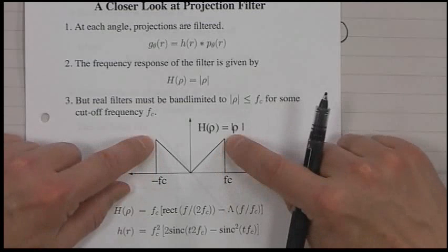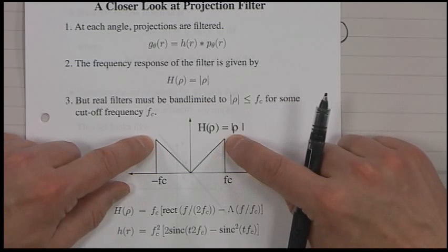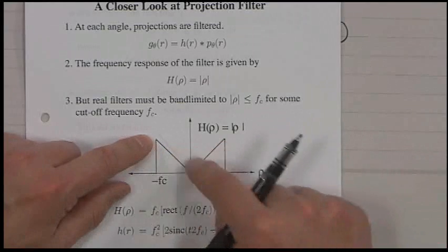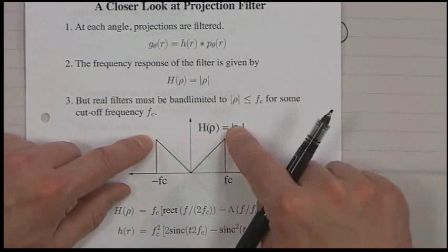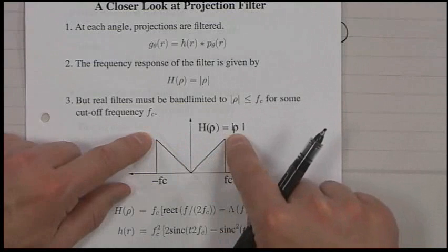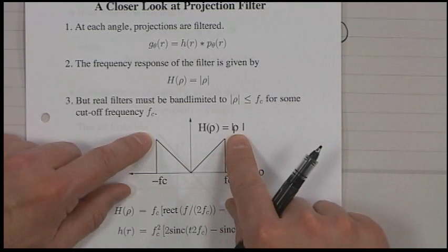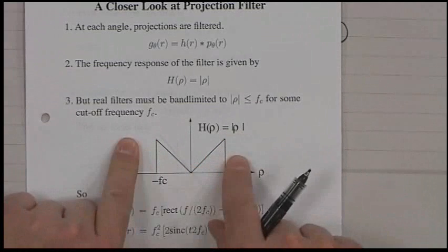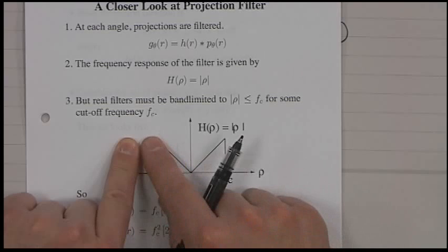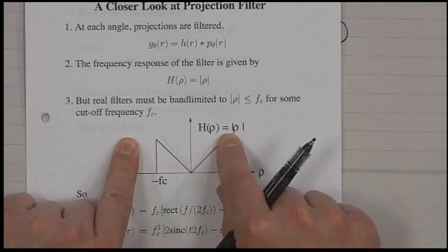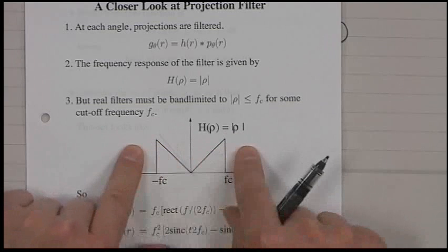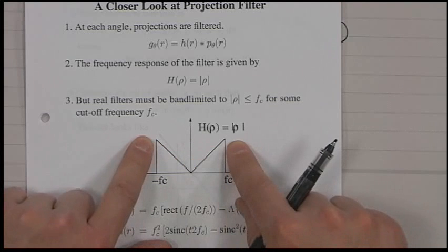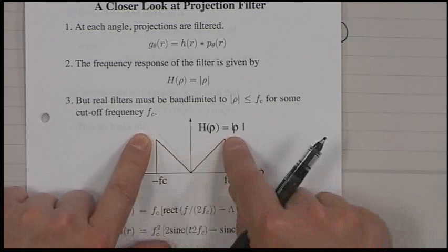You can take the inverse Fourier transform of that, and that's easily done because this is like a rect function minus a triangle function, and the triangle function is formed by the convolution of the pulse width with itself. So you can calculate the Fourier transform of both. The Fourier transform of the triangle function is going to be like a sinc squared, because when you convolve in time, you multiply in frequency, and the Fourier transform of the pulse is a sinc.